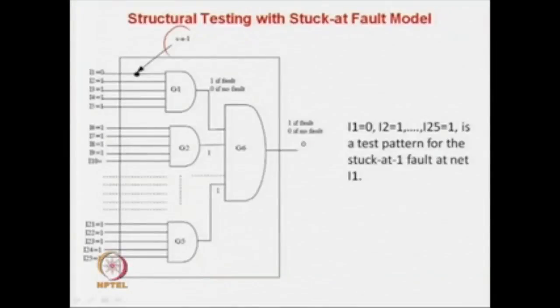that a stuck-at-0 fault is not there. Now, if you simply reverse it, say there is a stuck-at-1 fault over here, then I have to somehow apply a 0 over here. So I put a 0 in this case, and because of the observability, I put all 1 1 1 1 on the other inputs of the AND gate. If the circuit is normal, since you applied 0, the answer should be 0, and if this net is somehow stuck at 1, you will get a 1.